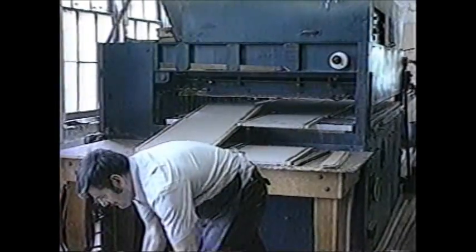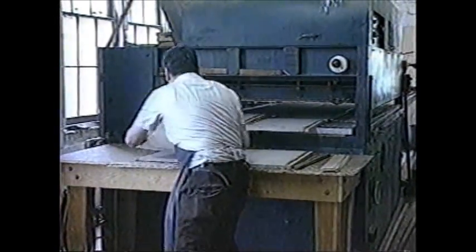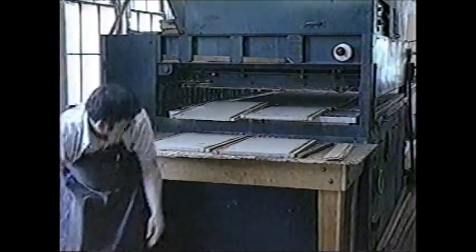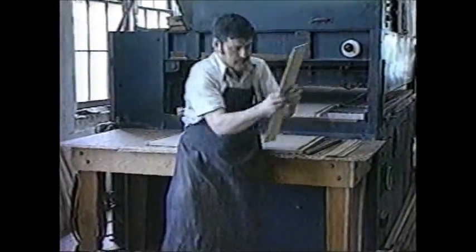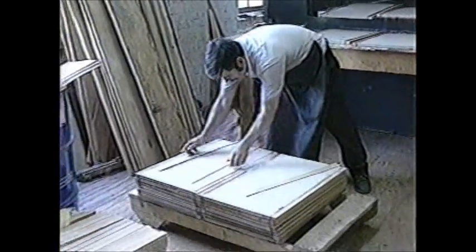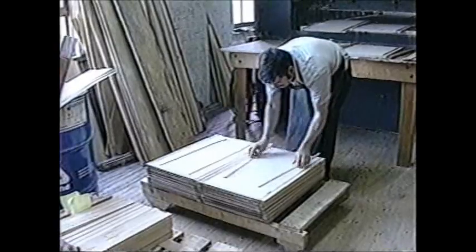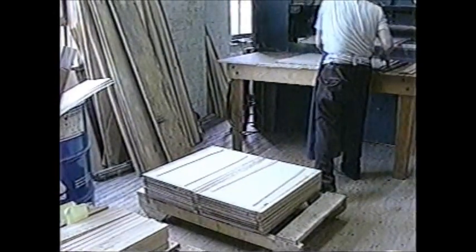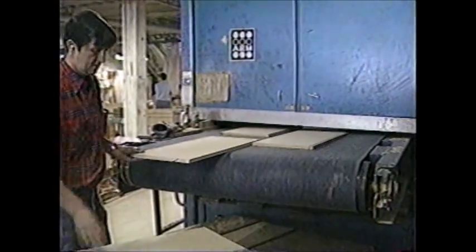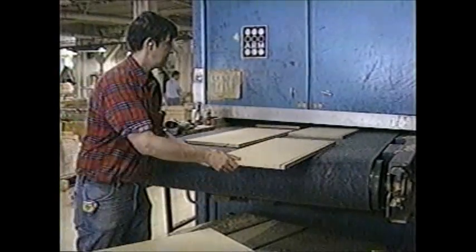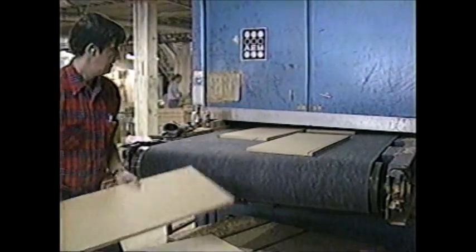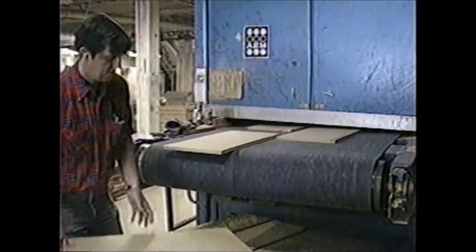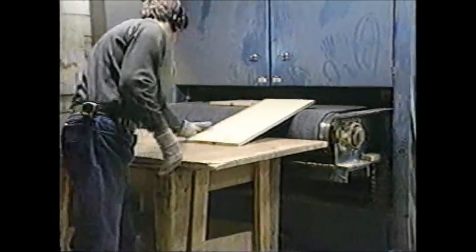Here, lumber strips are being glued to particle board cores in a hot press. The emerging panels are separated to cool and further cure before sanding and veneering. The edge-banded panels are sanded in an abrasive planer to achieve a specified thickness and to obtain surfaces satisfactory for veneering.